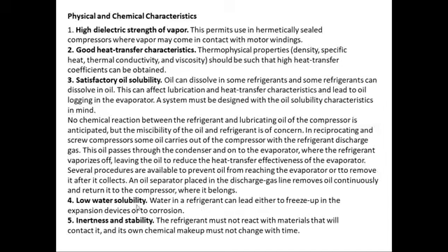So if there is water, it should be drained out. Water is not good for your refrigerating circuit. Inertness and stability. So if it has low water solubility, that means your refrigerant will not absorb water into it. So even if there is some exposure, it will not absorb the water and take it to the circuit.